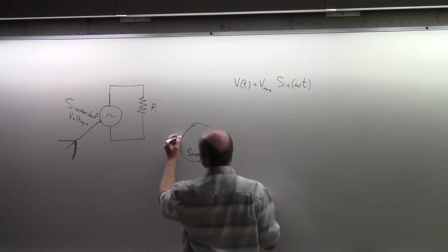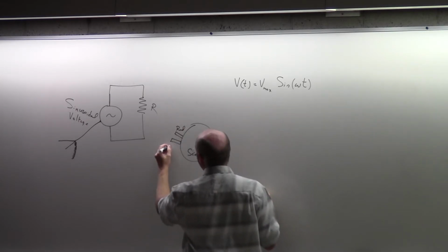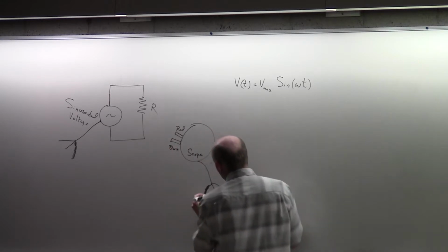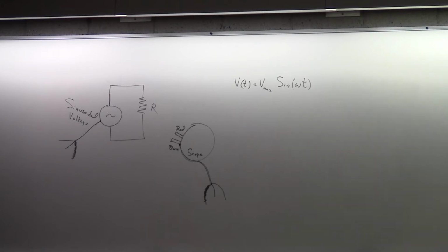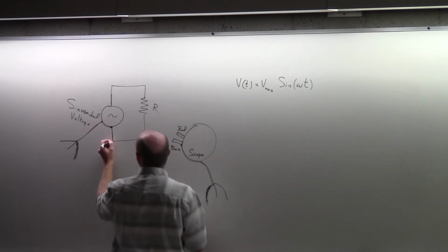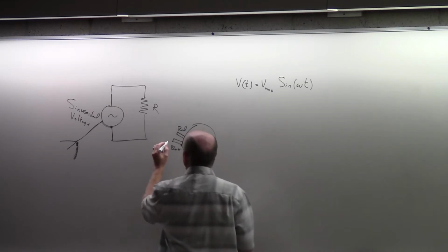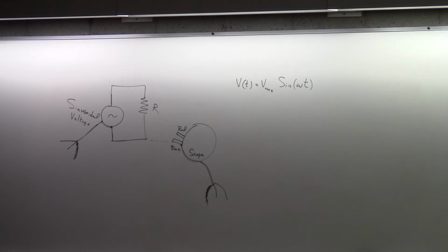And coming out of my scope is what we would call the signal, red, and the ground, which we would call black. And what you may not know is that those are hooked together. Although many of you do, because we talked about this in lab. But for the last of you who haven't done the lab today, that is actually hooked together. Likewise, the same thing happens in the signal generator. So I don't really need to hook the 2 black ones together. They are already hooked together.